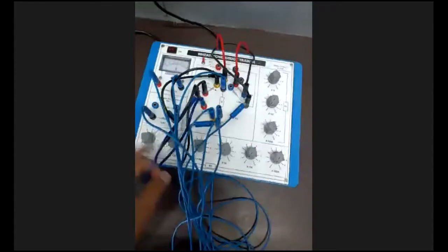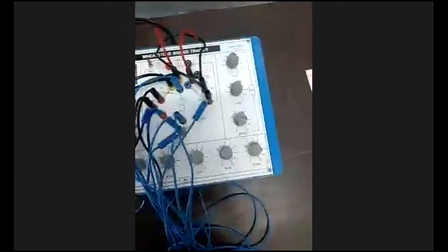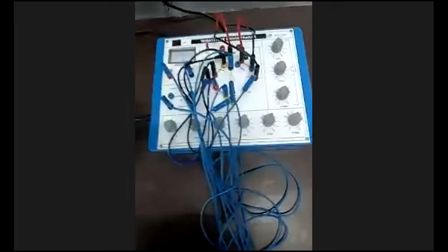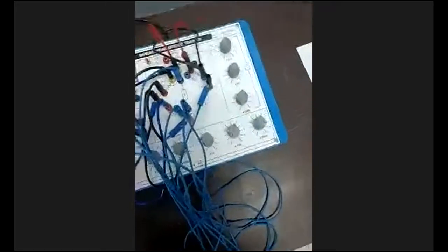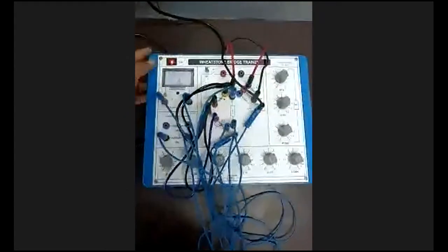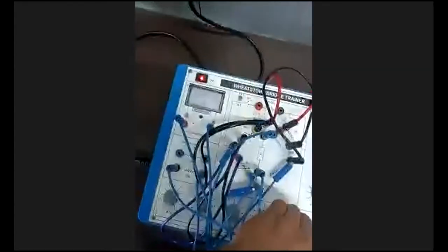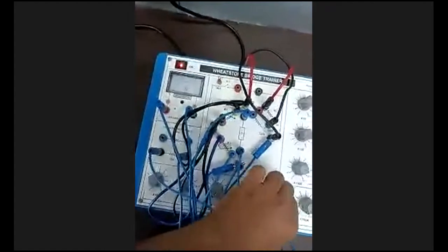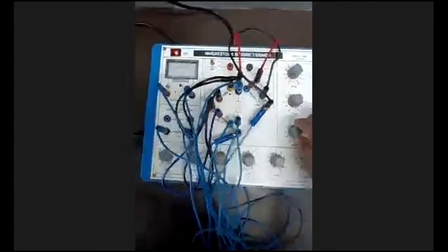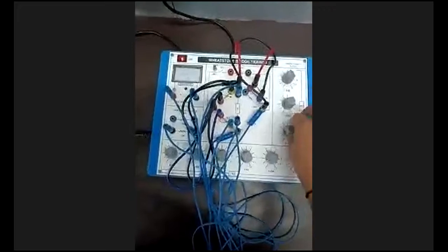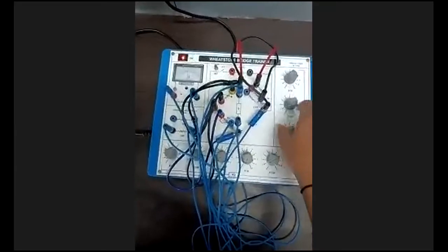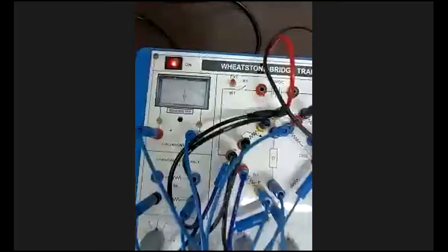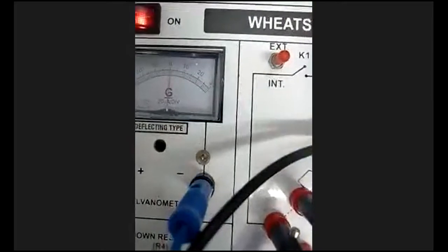Can I remove the connection? I want to see one more value once again. Here, instead of this 560, I will use this 1 kilo ohm. Just I will show how the galvanometer will vary here now. Here the galvanometer is at a different value, no? Yes or no? I will show the full picture here. You can think that here the R1 came to 0, but a little bit is there here now.